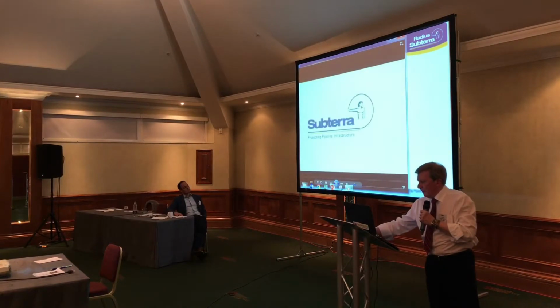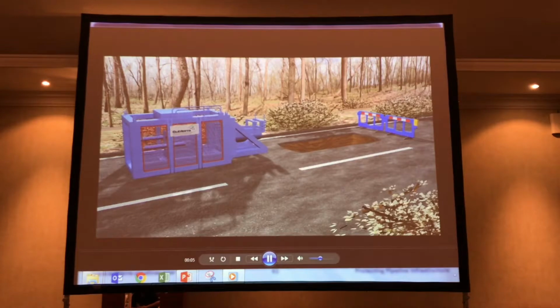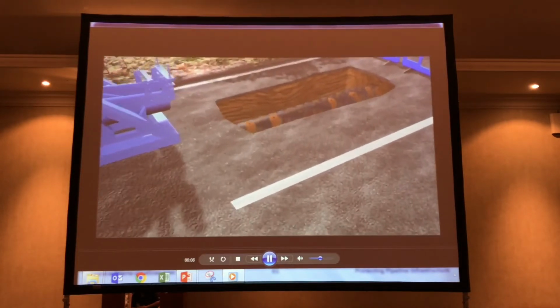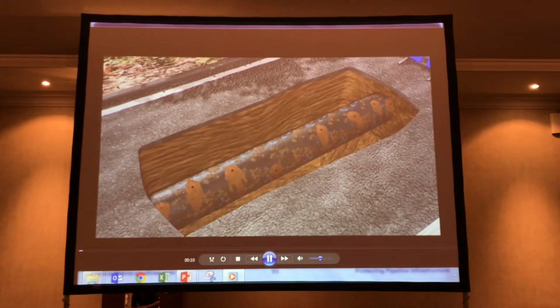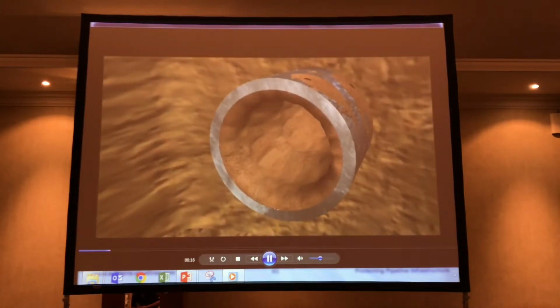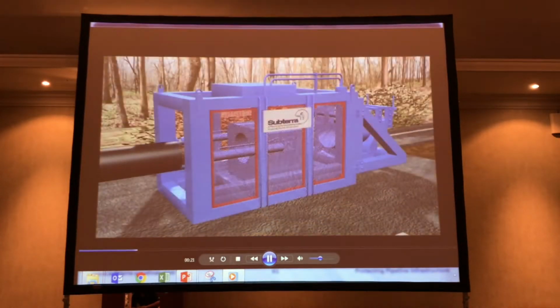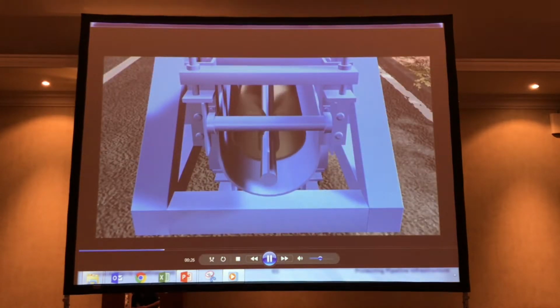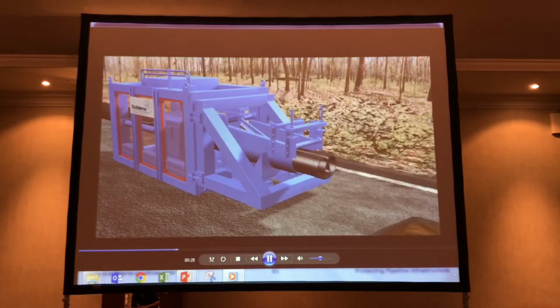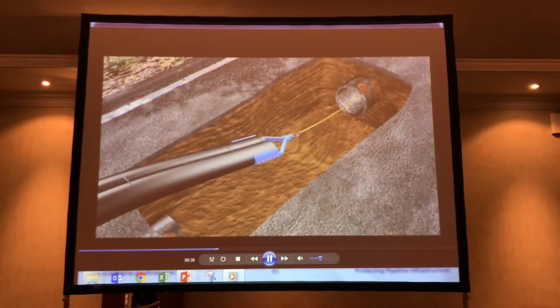So this again just illustrates it requires two pits to be cut in the ground and break into the pipe at 2 points, an entry and a reception pit. The pipe has to be cleaned out, any obstructions removed. The liner pipe is then fed through the machine which folds the liner into the U shape. The shape is retained with straps. A towing head is fitted. The liner pipe is then drawn into the host pipe.